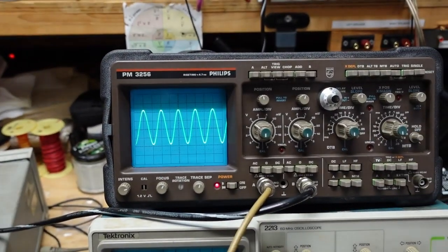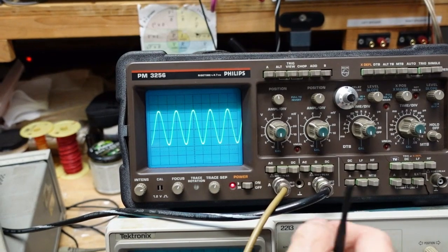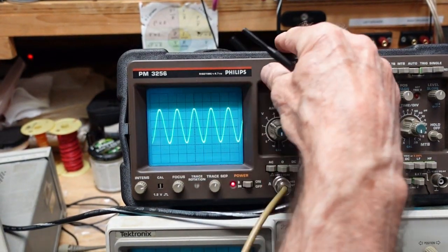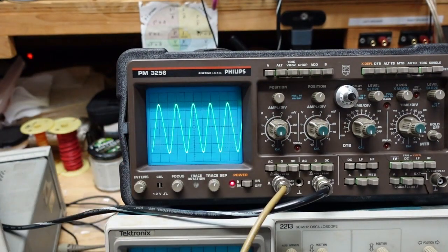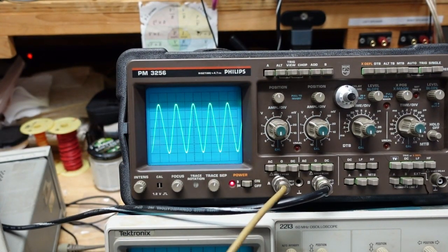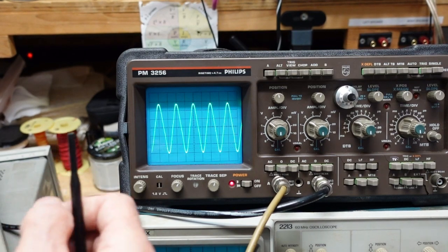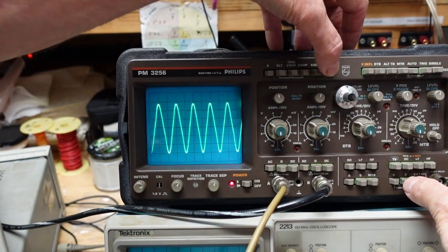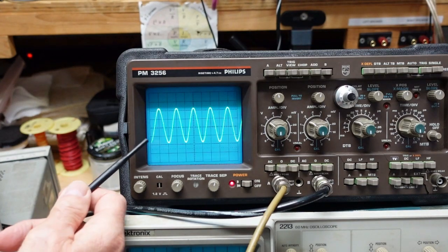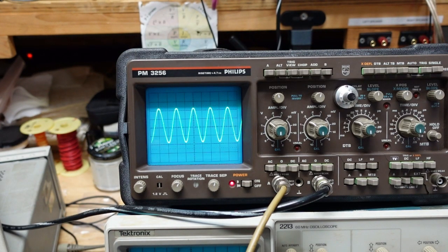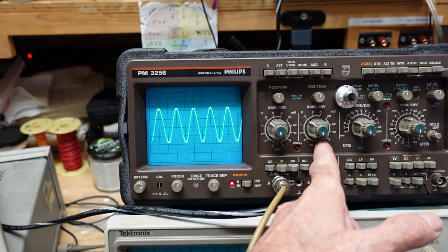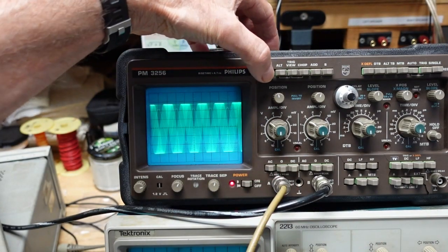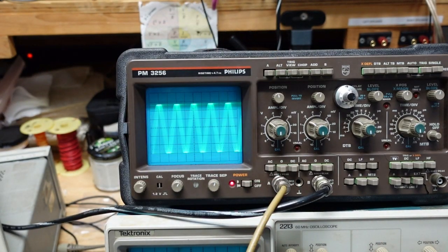And what we do is we look at our scope and we are going to observe channel 1. Okay, so here's channel 1. That's coming out of the frequency counter. If we look at channel 2 is the 10 megahertz from the GPS disciplined oscillator. So we want to leave our trigger on B, or channel 2, but we're going to look at channel 1. And as you can see, we don't have lock.